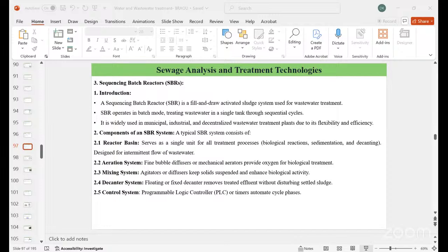Coming to residual disinfection, some disinfection methods provide residual disinfection, which can be beneficial for preventing growth of microorganisms in the distribution systems. Another consideration is the cost and the energy consumption. The disinfection method should be chosen based on its cost, energy consumption, and the purpose of the treatment. Also, the environmental impact of disinfection byproducts and residual disinfection should be evaluated. And local regulations dictate the required amount of disinfection.